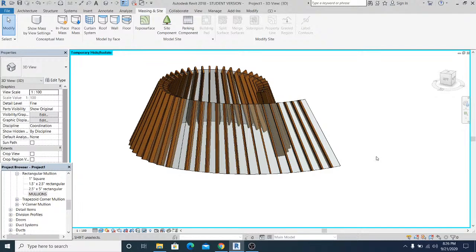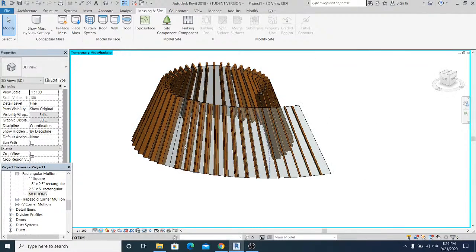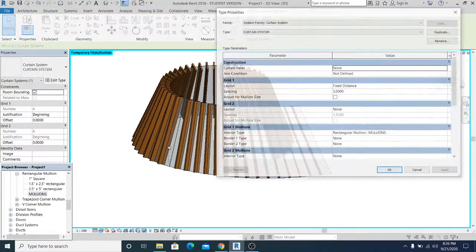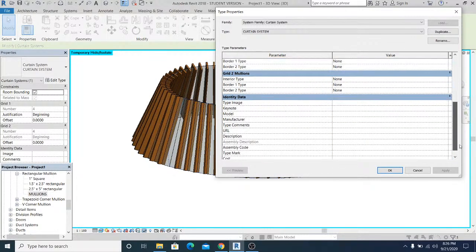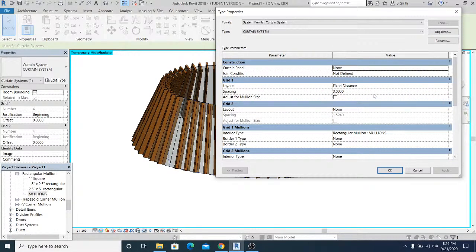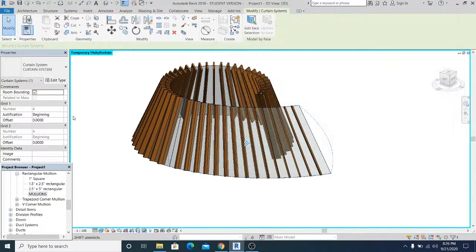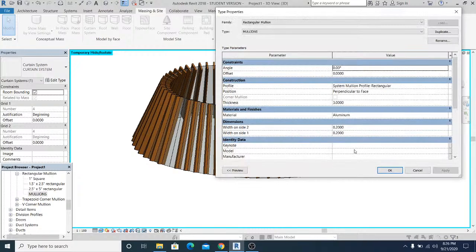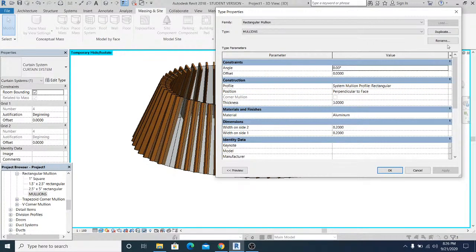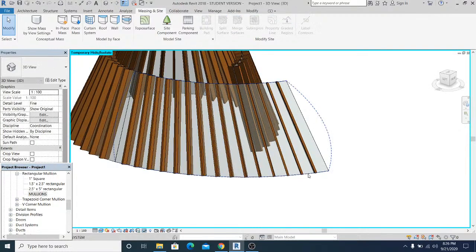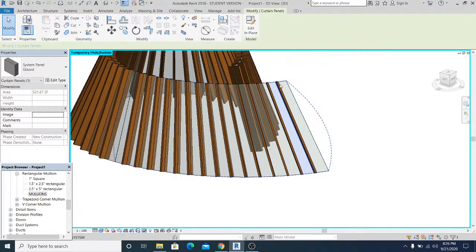You need to create the mock-up as a mass before you make the mullion curve. And you can modify this also. The glass glazing, you can change it in the properties. For the mullion, it's better to hit Tab to select only one of these.